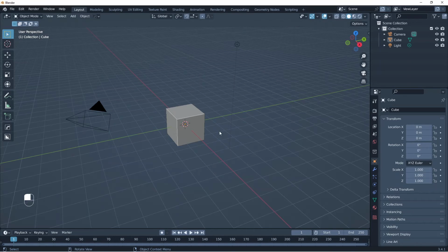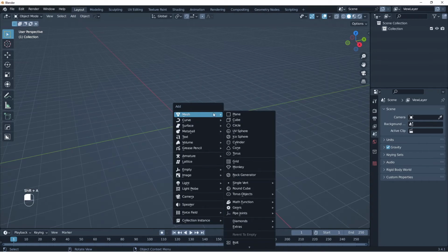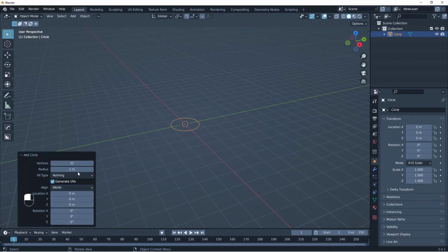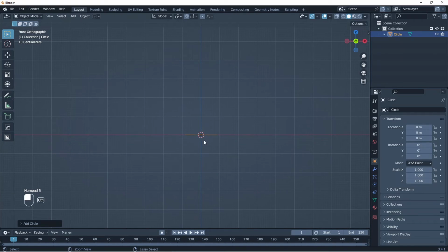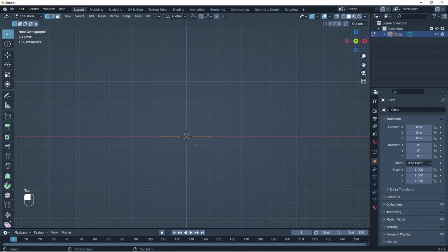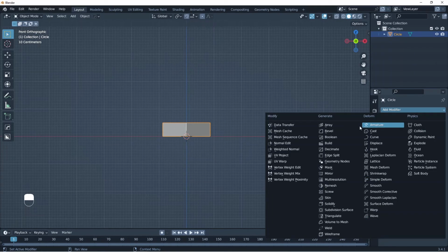All right, let's just dive into Blender. We're just going to delete all of this, and we want to create an object that can repeat infinitely. So I'm going to create a circle with only 5 or 6 vertices, a hexagon. Go to my front view, and we really want to be very precise when doing this. So I'm going to show you how to be precise when extruding. I'm going to extrude on the z-axis, and I'm going to press 0.5. So if this is 1, then we're just extruding it 0.5, like half. We need to remember that because later it's going to be of some use.